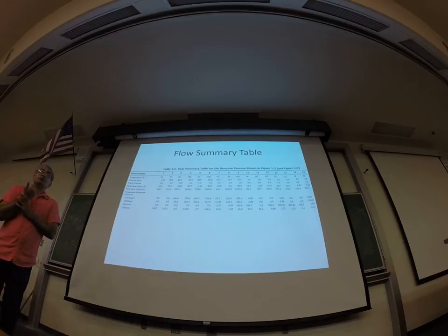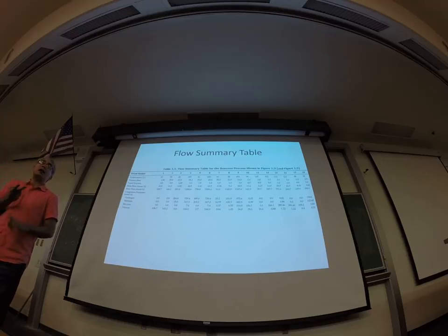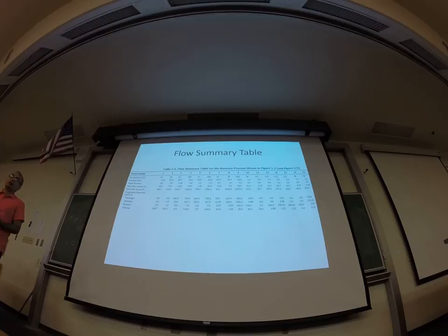You have to think very carefully on scaling up. And by carefully, I mean you have to think about the heat transfer, mass transfer, fluid mechanics, thermodynamics, kinetics, and how that could change. Are there any recycling issues? Are there any stagnation region issues? You have to really think carefully when you're trying to scale up from the benchtop data.